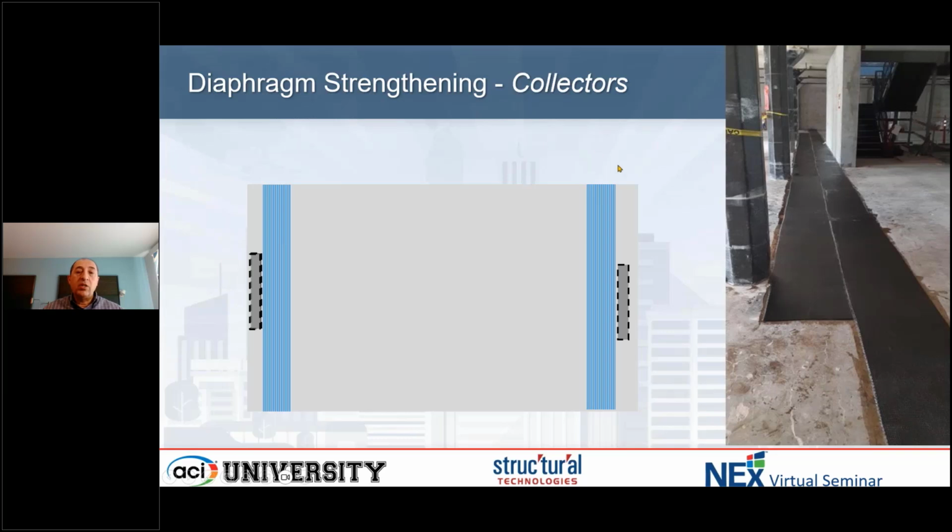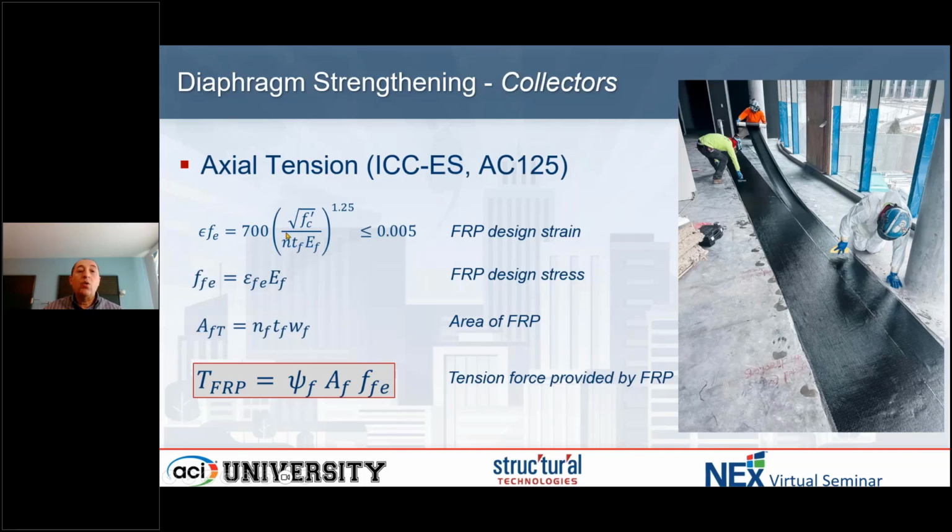In terms of design strain, if I look at that floor slab that we talked about, then the FRP would be applied similar to mimic that steel required for that collector. The design requirement is a little bit more aggressive, so less strain. I'm utilizing less FRP because from tests, from experience, we know that FRP under axial tension typically gives you less capacity than when it is applied in bending. It's similar to concrete in bending, which has higher tension capacity than in pure tension, right?